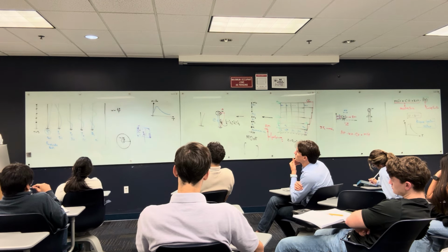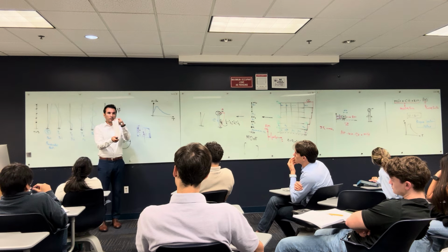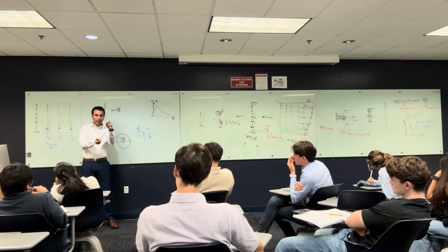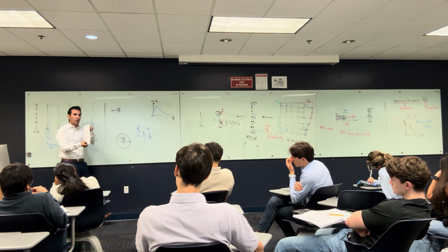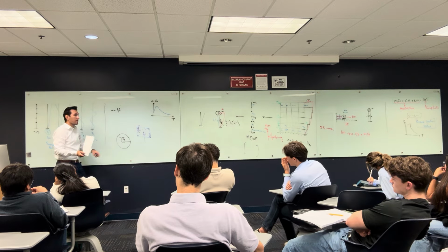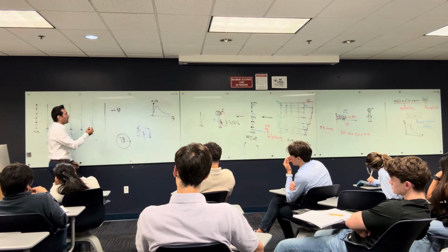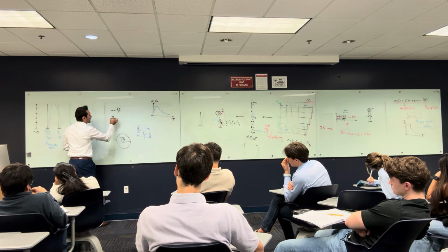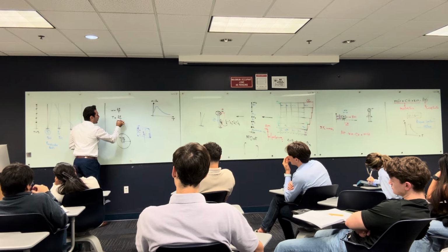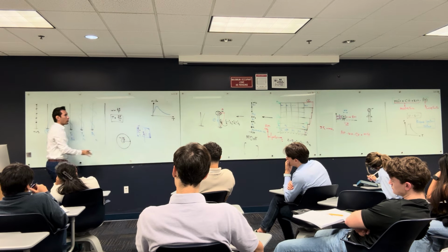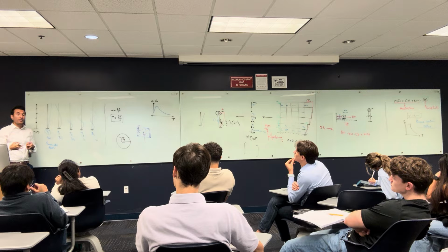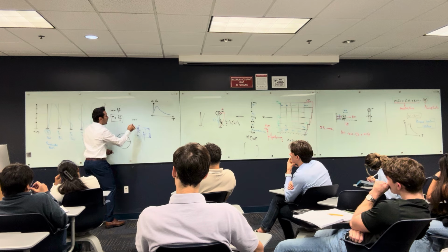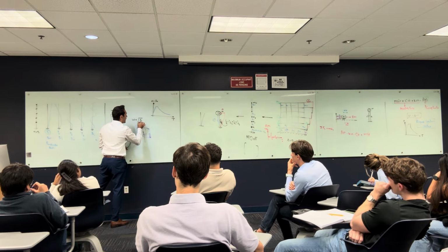Same thing happens here. By the way, if you try to track the displacement that happens here, it's gonna give you a circle. You are gonna go that way, and you are gonna come back to the original place. So you get 2 pi over t, and that's equal to the frequency, the radial velocity. So then you can say that t is equal to 2 pi over omega. The period of the structure is equal to 2 pi over omega, the radial velocity of the structure. And it was proven that omega is equal to root k over m.